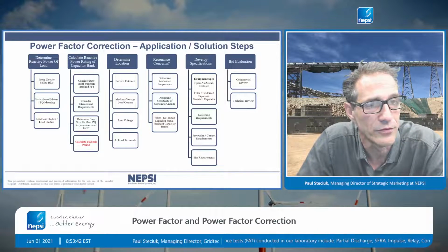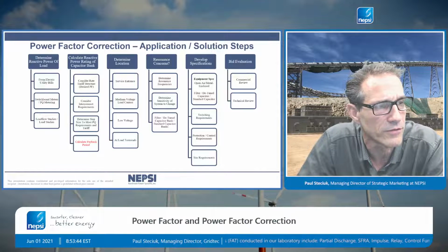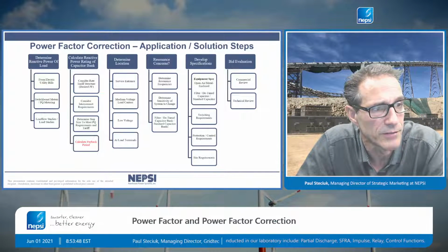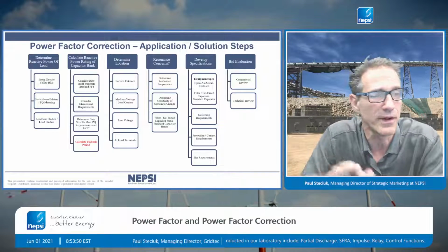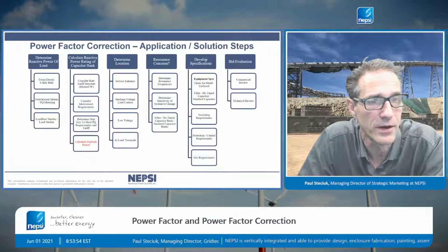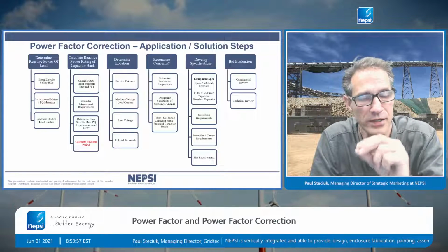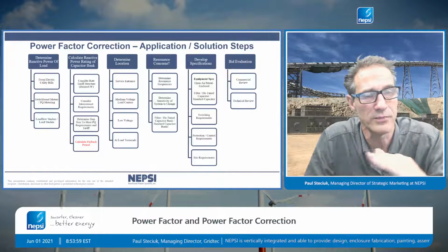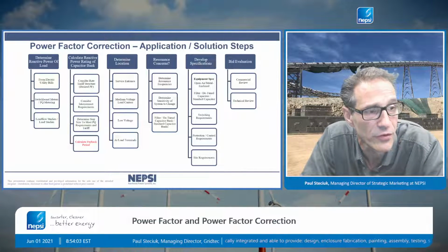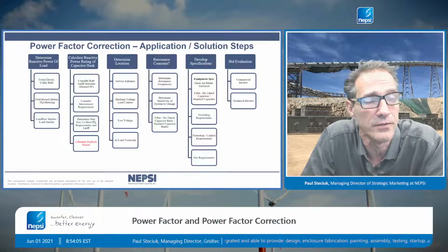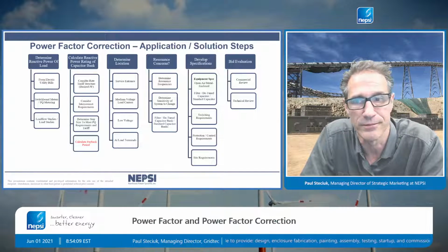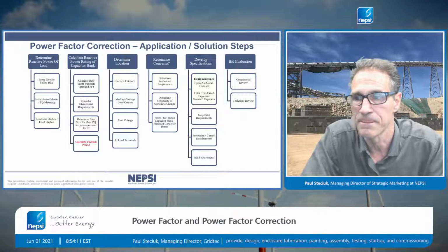I have to look at the interconnect requirements if it's a renewable plant, and determine how many steps of capacitor banks I need. Step size is really dependent upon how much voltage rise I can get, and also do I meet the power factor penalty requirements of the company I'm doing it for, and then I calculate payback. And really, the decision to buy capacitors is an economic decision.